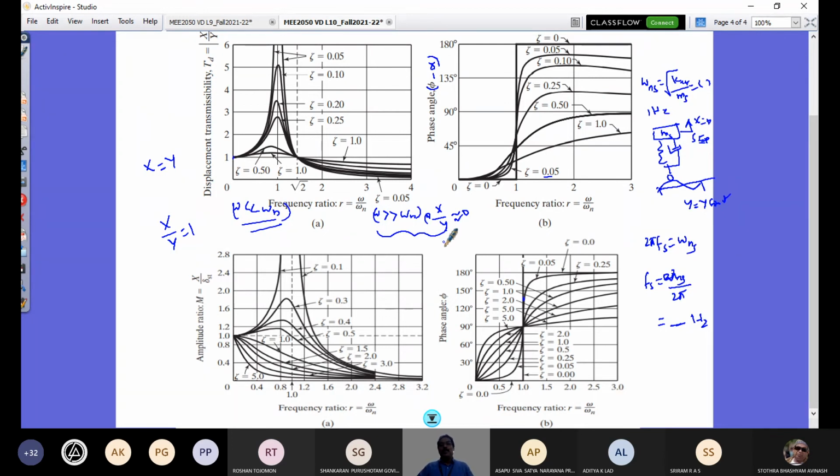Right, there is no road profile, but still you could see on a road surface the waviness of your vehicle. At that time, when you are driving at high speeds, your vehicle would appear to be bouncing, that you would experience, right? So look at both the graphs, and importantly here, look at this point: all the curves pass through it, and you see this transmissibility irrespective of the damping present in your system. The damper is part of your suspension.